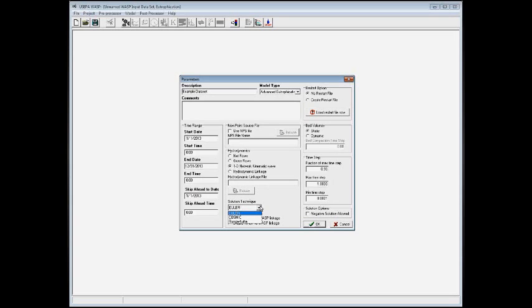There are a couple of other options. The cosmic option is used when you're linked to three-dimensional hydrodynamic models like EFDC. The Runge-Kutta could be used if you've got sharp diel variations that you need to be more stable around. I'm going to leave it as Euler.